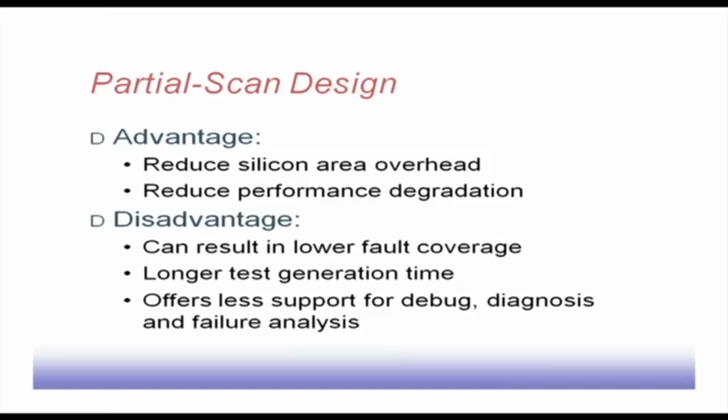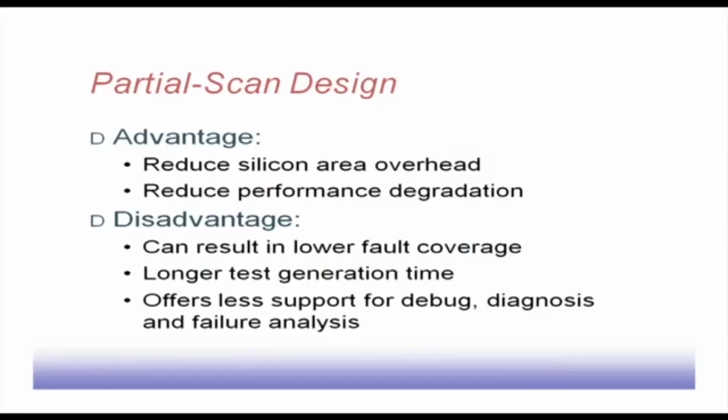Disadvantage: it can result in lower fault coverage, because we do not have control over all the flip flops. So naturally there may be a fault coverage problem. Test generation time may be longer, because in many cases we have to use sequential ATPG, and sequential ATPG algorithms take longer time to run.